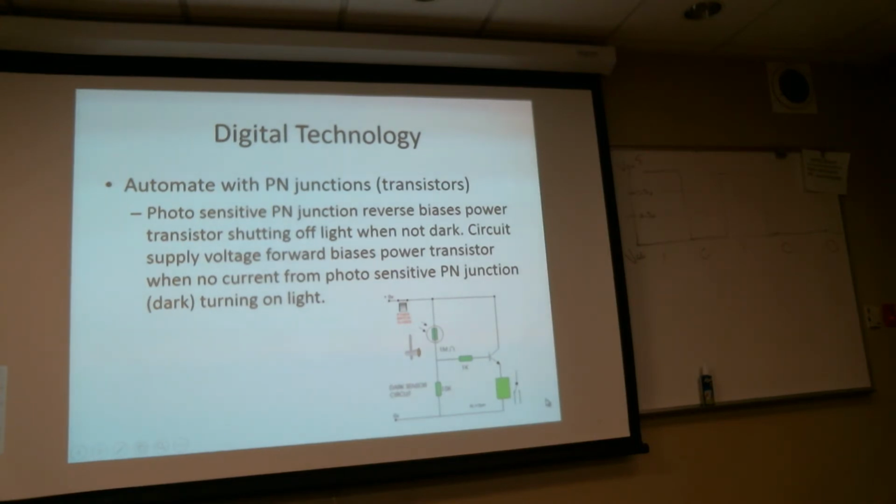So a lot of times we just use those two references, VEE and VCC, or VGG for ground, one or the other, to indicate whatever the power source voltages are. And then you go over the spec sheet, and the spec sheets say VCC can be anything from. So it's called a variable.